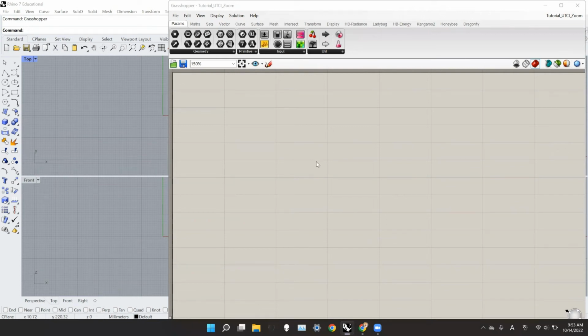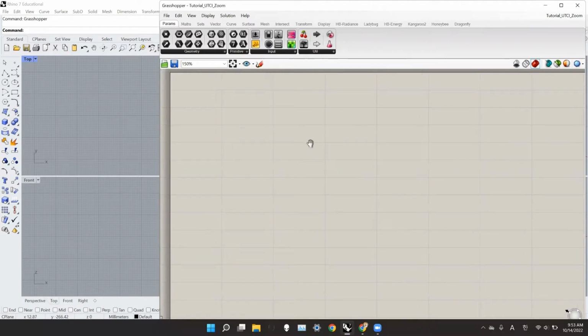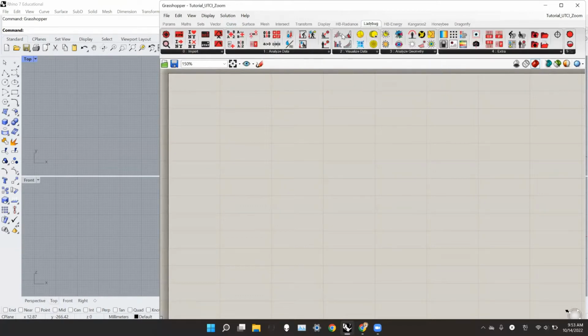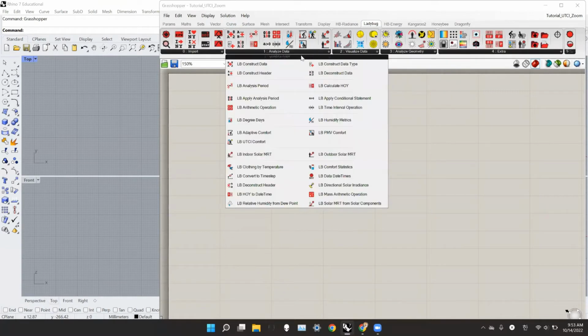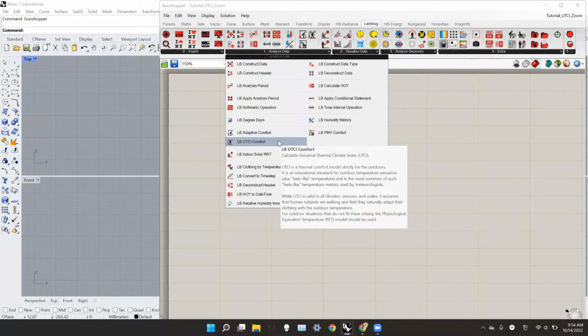This is Jean, and I will start the tutorial for the outdoor thermal comfort analysis. I talked about UTCI yesterday to analyze the outdoor comfort. What we need is to look at where the UTCI component is. Under the analyze data, you can find the UTCI comfort.